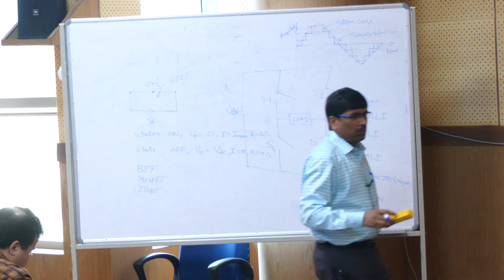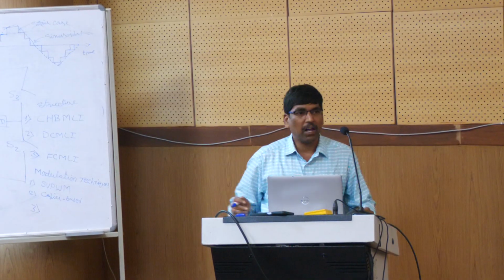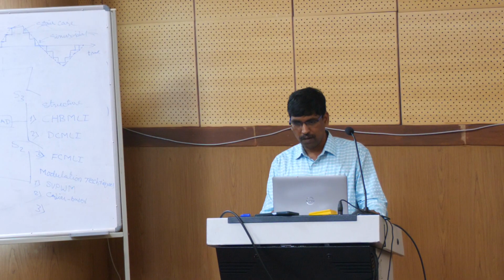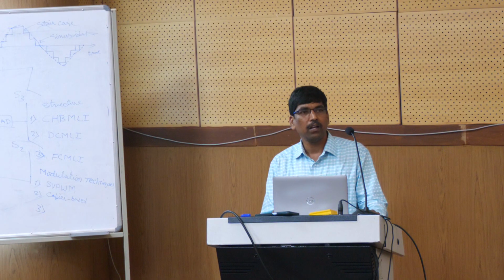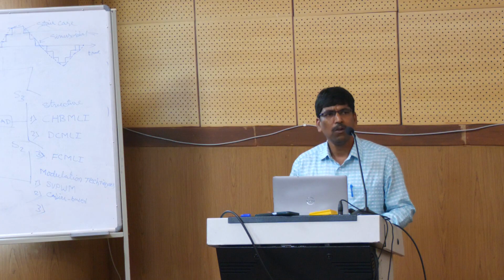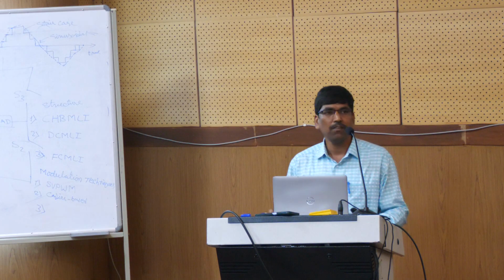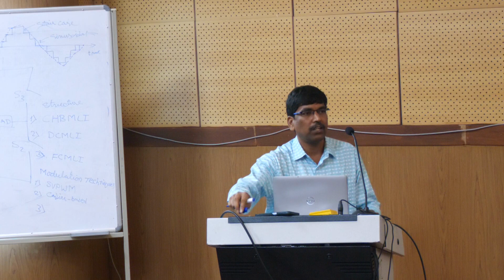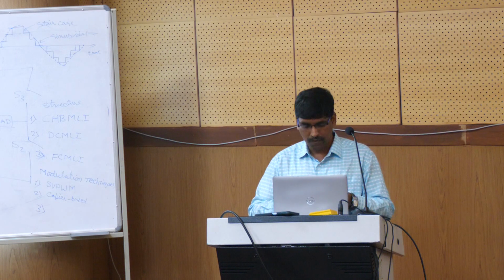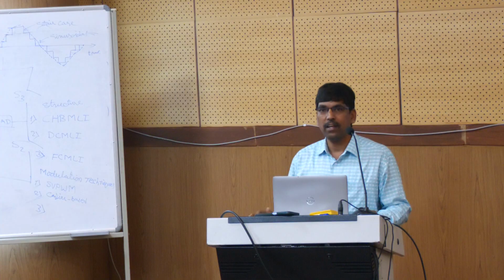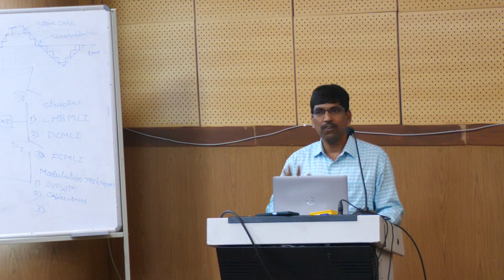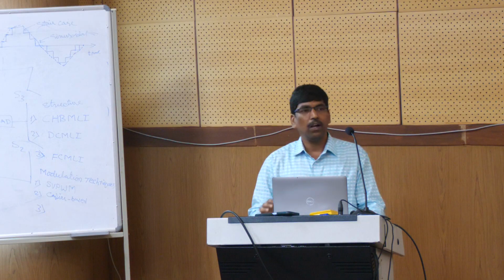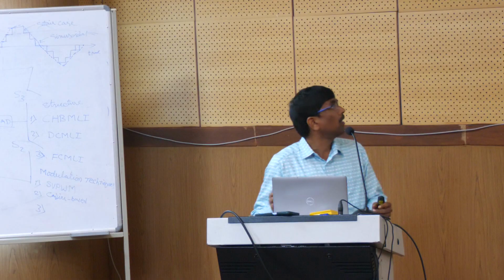Now the maximum rating of this one is also restricted to 3.3 kilovolts, with a current rating of 500 to 600 amperes being the more advanced one, we can say. For the rest, if you want to go for high power ratings, we have to have series connection of the devices. This is the overview of the things that we are going to have. If you see, when it comes to this kind of things.